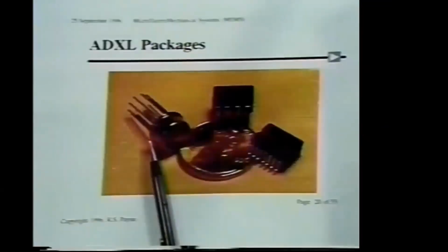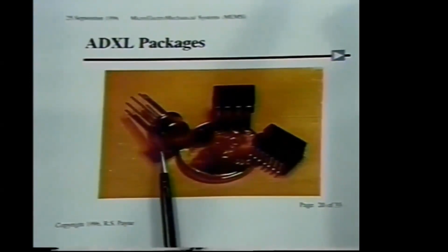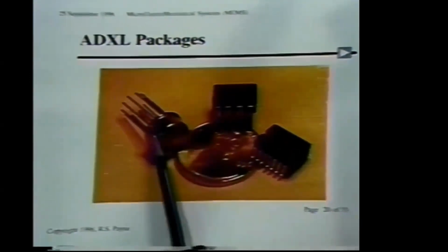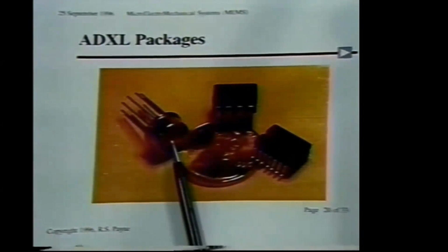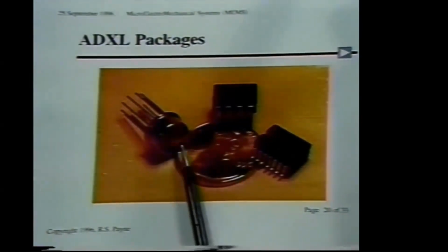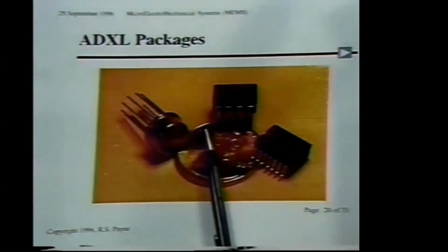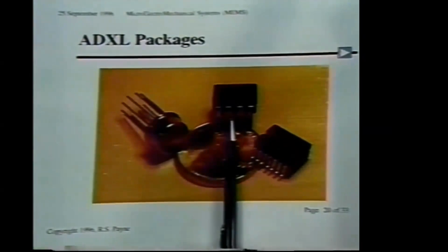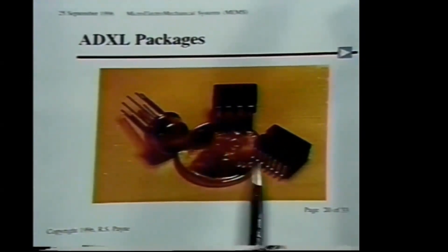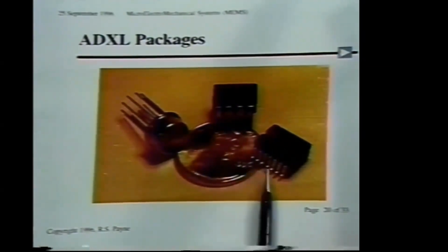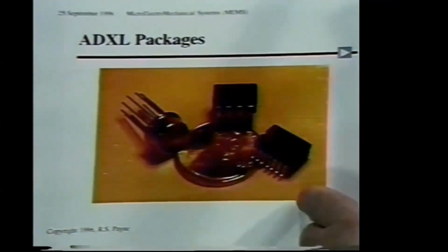The initial package, which was in a hermetic can, had the attribute that it's essentially welded. And so the properties of the device, which are established at room temperature in testing, were preserved very well through the process into the back end. But this device cannot be automatically assembled. Again, a feature that I'm sure many of the mechanical engineers in the audience can get involved in, in terms of integrated circuit automated assembly into PC boards. So DIP packages, in this case an 8-pin through-hole mounted DIP, and soon to come a 14-pin surface mount device, were used for the packages.